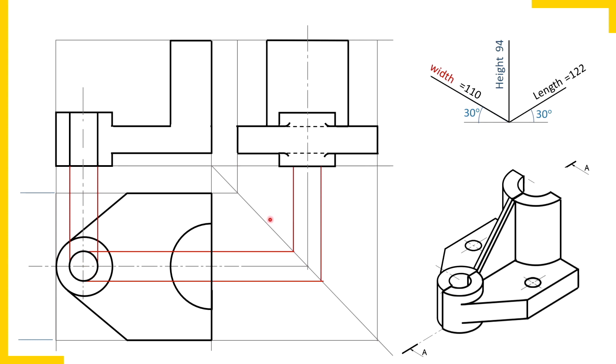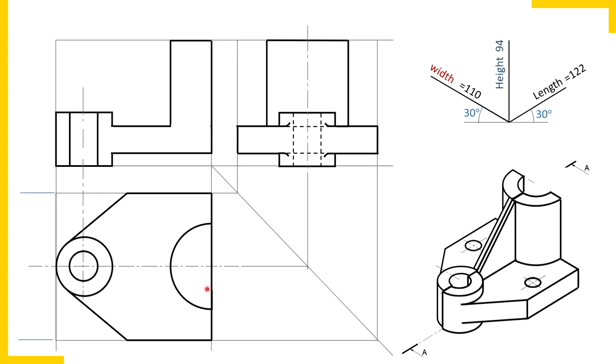As usual, I have projected it. The diameter is 22 millimeters. So you can measure here 11 millimeters and 11 millimeters independently instead of drawing these projectors. And then dotted lines. So the hole is of course hidden from the left side. Okay, so the hole is hidden. So we have completed the hole in all the three views. Now there is a semicircular slot in the semi-cylinder. Let's draw it. 18 millimeter radius, and I have made the semicircular slot.